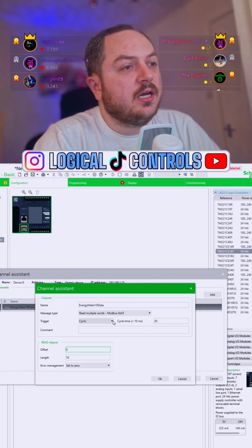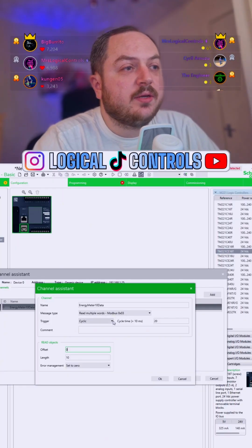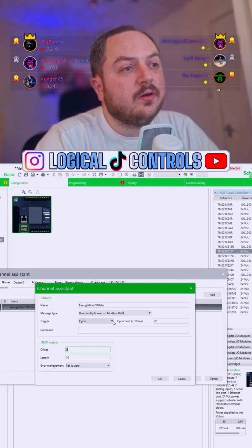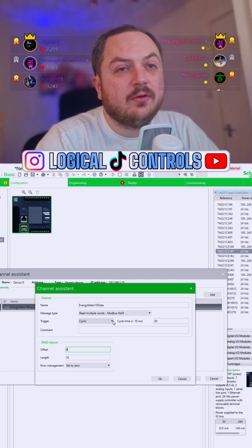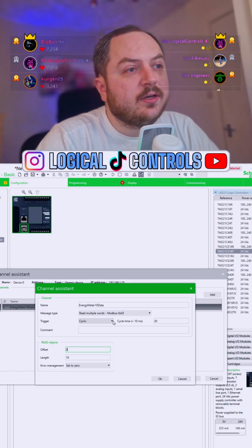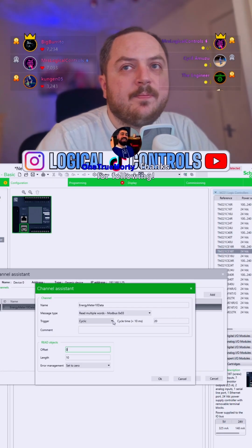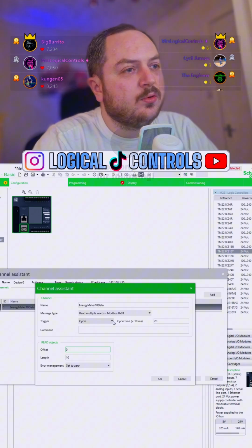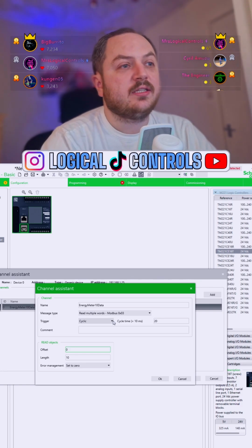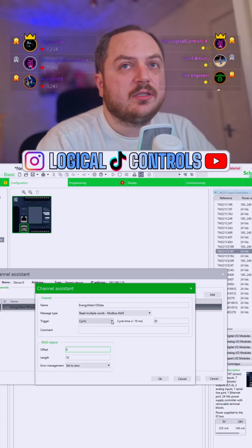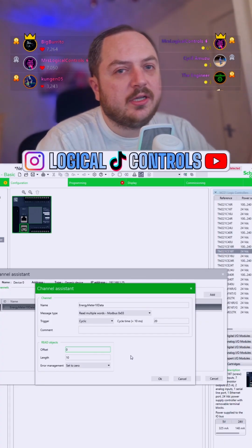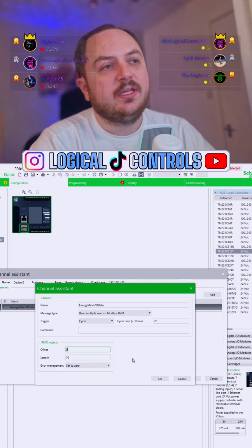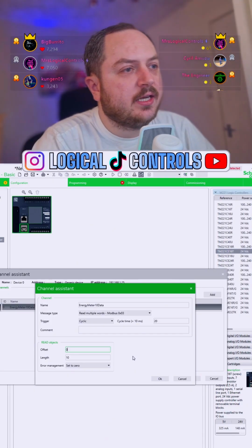How do you connect Modbus RS485 to a Profibus network? You would need a converter. They do exist, because I do remember using one maybe about a year ago. I don't know a great deal about Profibus. I think Profibus is easier by the sounds of things. You generate a table of information, and then you just import that table on the other end, whereas Modbus needs to be set up on the server or slave side, and then you need to re-enter all that data on the client side.